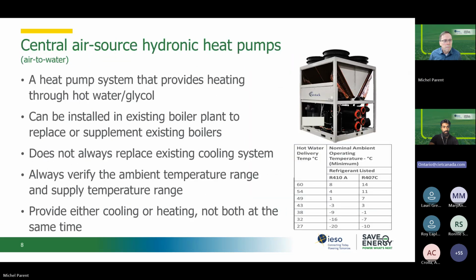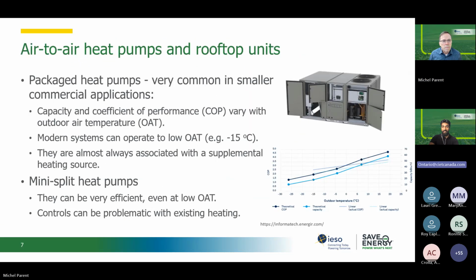It says back in slide 7, the COP and capacity curves for the air heat pumps, why does the actual versus theoretical line show very different slopes? Well, it's because manufacturers test under steady state conditions, whereas with heat pumps, if it short cycles because of the actual transient behavior of the system, the transient behavior is never as efficient as the steady state.